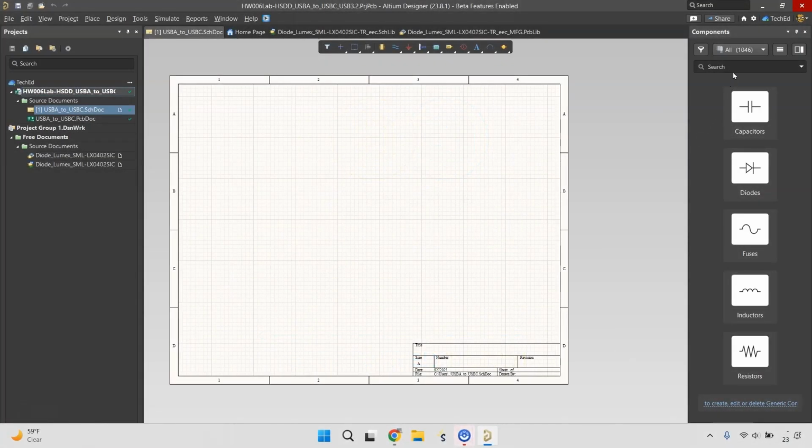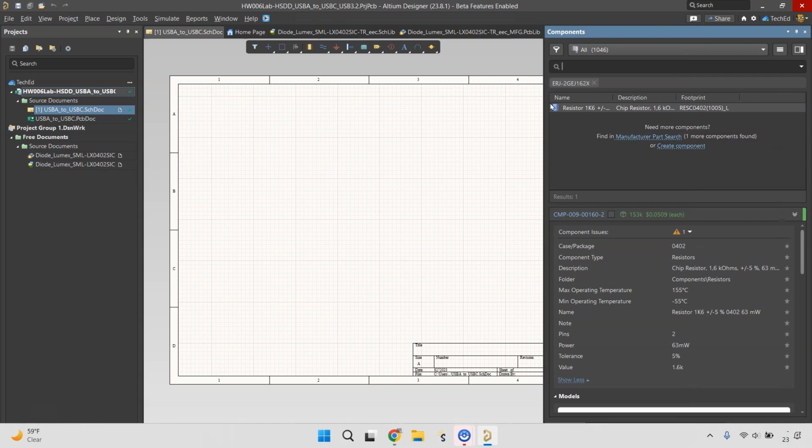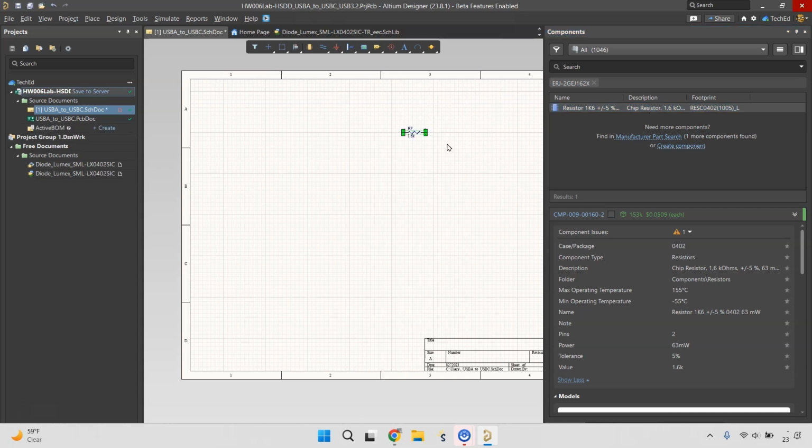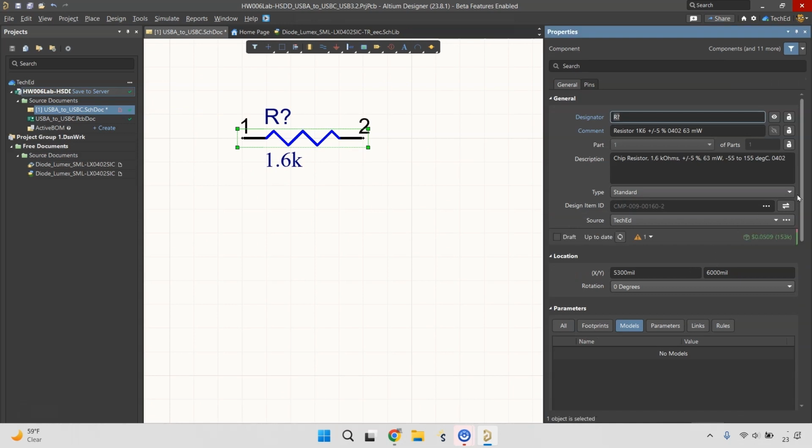and we are looking for specific resistors. Now we are in the components library, or we're looking in all of our libraries on the Altium 365 workspace. And I see here that this component might be the manufacturer part number we are looking for. I'm gonna drag that over here, double click on the component and see what properties this has.